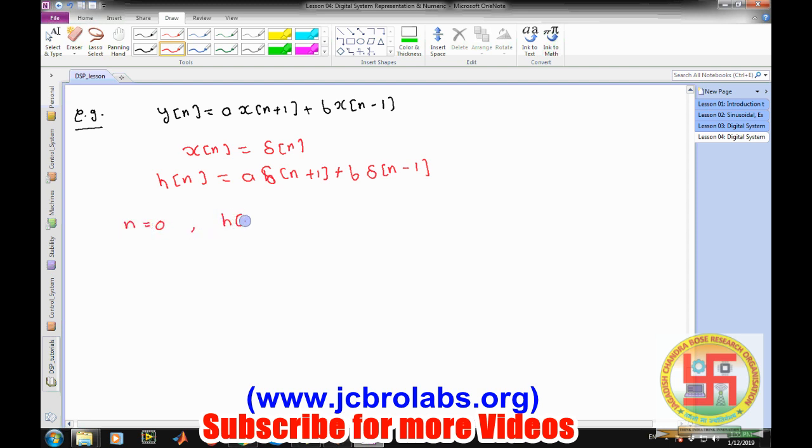this h of 0 will be simply 0, because it will be a into delta of 1 plus b into delta of minus 1. Both will be zeros, right? So h of n will be 0 at n equals 0. At h of 1, that means n equals 1, this one will be b only, because ultimately only this signal will have some value.